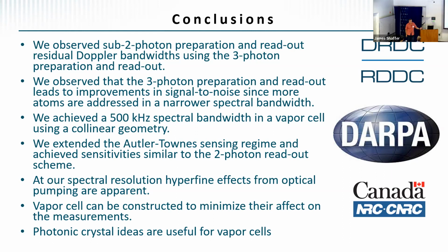So there's also a materials issue too, which we constrained ourselves to in this design, which was that we were going to make the frame out of silicon because of the bonding that we use. We've recently developed, which I can't talk too much about, similar low temperature bonding schemes for glass on glass, and those will be better because then we'll be able to better match the index of refraction, and those cells will be even better than the one that I showed there. I think I answered that. Yeah, so uniform in field.